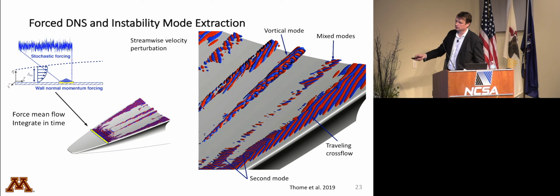So this is probably just noise: there's amplification in the boundary layer, and we're just plotting one magnitude of the streamwise velocity perturbation. If you were to plot a range of magnitudes of velocity perturbation, what you'd see is this disturbance dying out and then seeding a new disturbance, because it hasn't gone away completely.